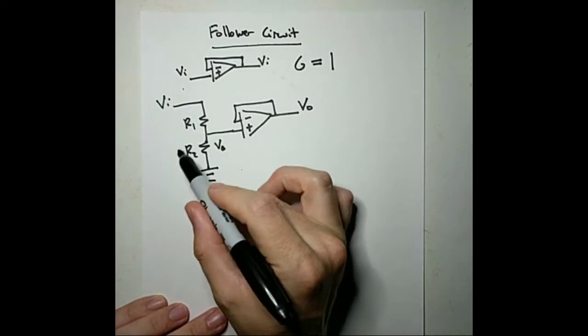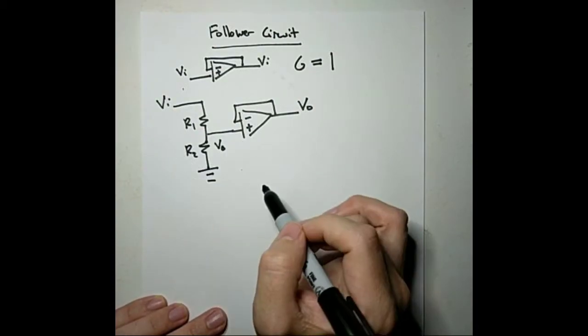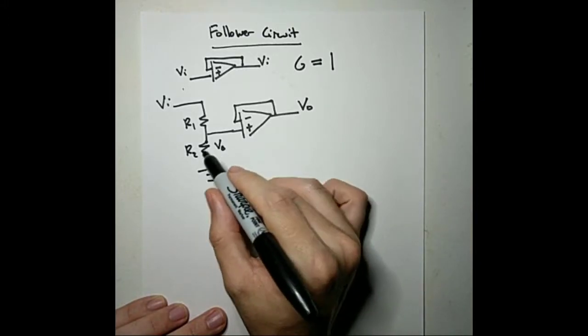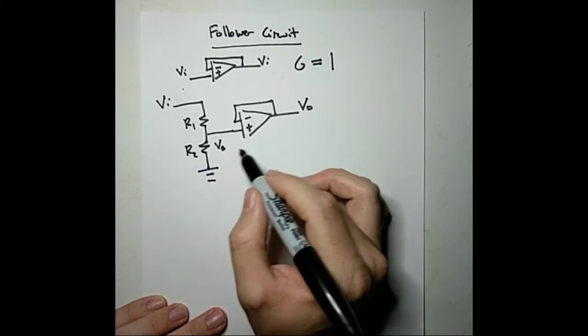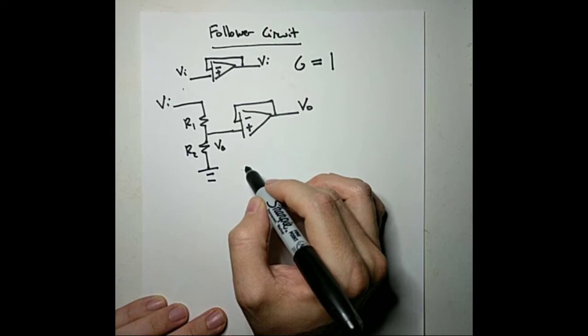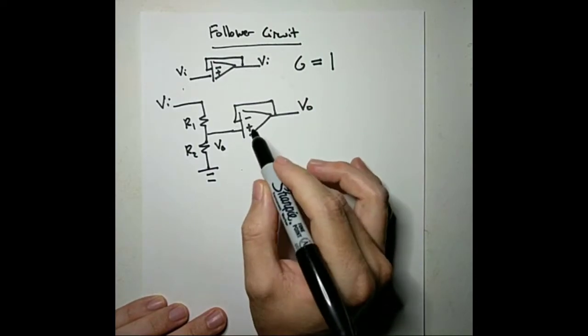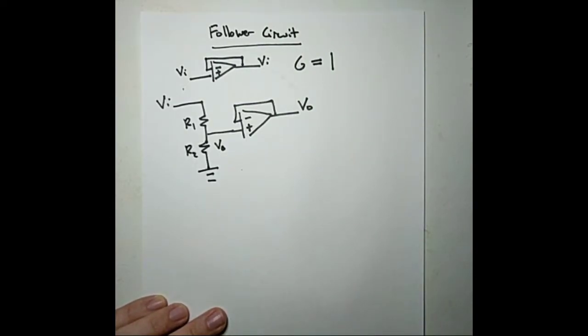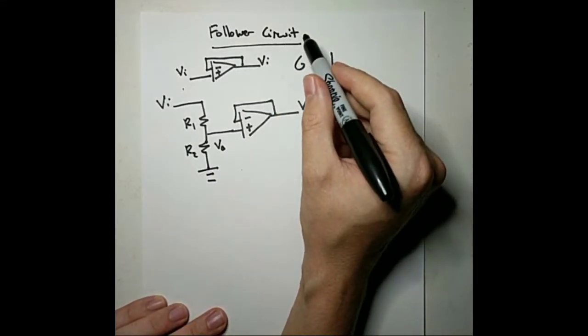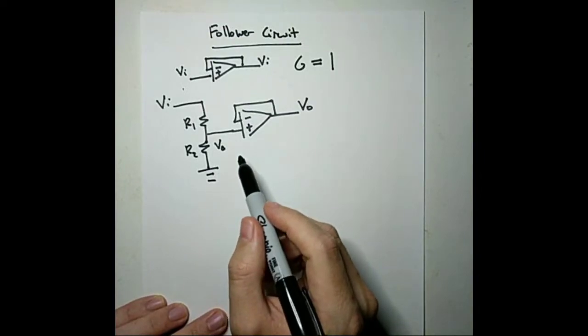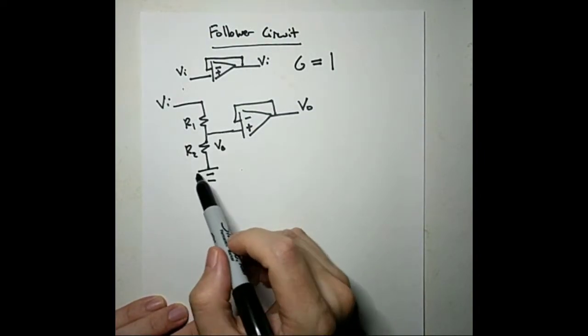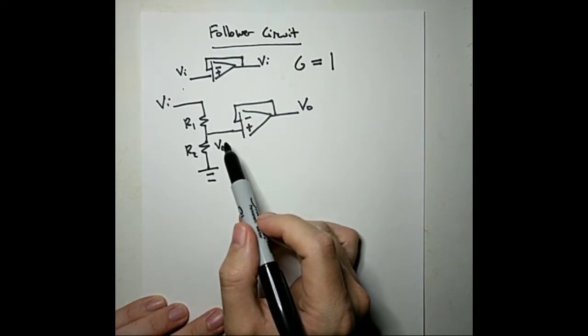We don't change this resistance at all, because if we think about that as an R equivalent thing, we're putting 1 over infinity. So it's 0. So we don't change that equivalent resistance. It still just is R2. So that's the use for a follower circuit. We can get a voltage drop without loading the resistor.